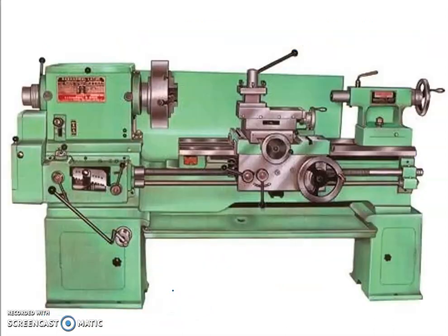We can see that in the diagram. So this is the lead screw of the lathe. This lead screw is used only while doing thread cutting operation. We'll discuss the different operations performed on the lathe later. So here the screw rod or the lead screw has screw threads on it. We can observe the square threads on the lead screw. And during thread cutting operation we can move this carriage assembly automatically left side and right side so that we can do the thread cutting operation.